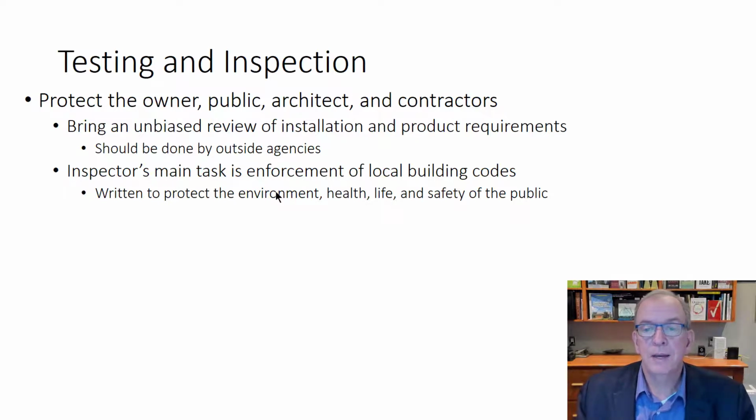So, testing and inspection, and we'll talk about this more with commissioning. And the third part, you want to ensure that whatever it is has been tested. That's why you have building inspectors. That's why you have engineering consultants. That's why you have testing and commissioning agents. It's a third-party review to ensure that what was designed in the specifications, which set the scope, which should set the expectations of what the client wants to receive when you're done, is being met. It's being verified.